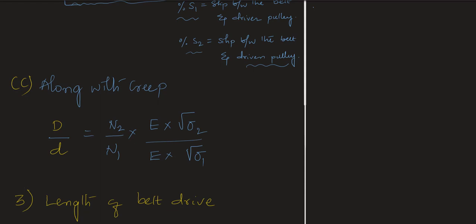Since the belt wraps the pulley continuously when under service, there will be tension on one side and slack on the other side, and due to these sustained tension forces, stresses are induced in the belt.